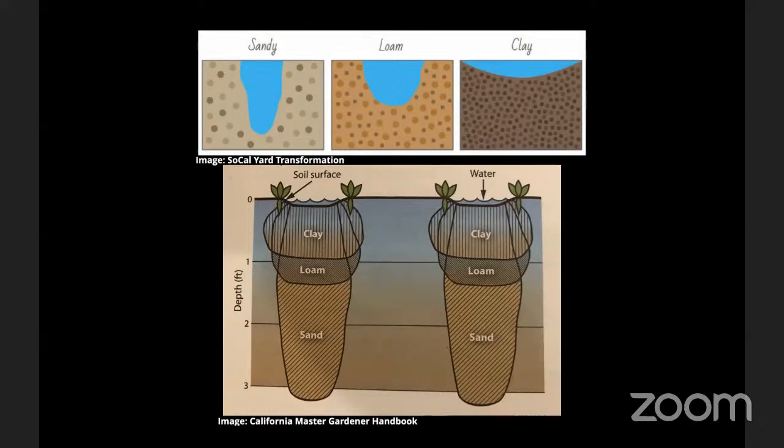Good question. They are connected. If you have super high pressure, like 150 PSI, it will be shooting more water through the line. However, once you get it down to the pressure that we are looking for, that 40-ish PSI, that's still not going to cause a huge restriction.